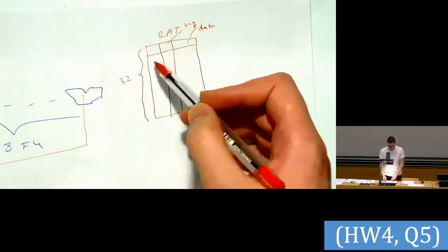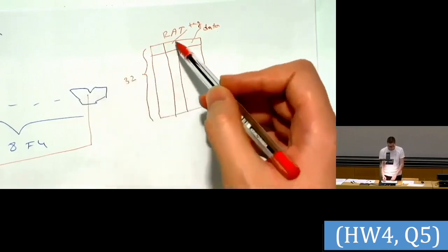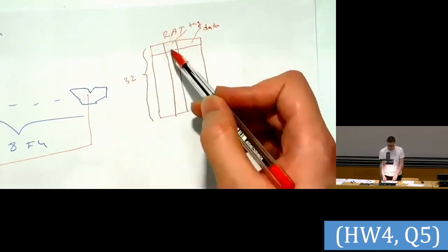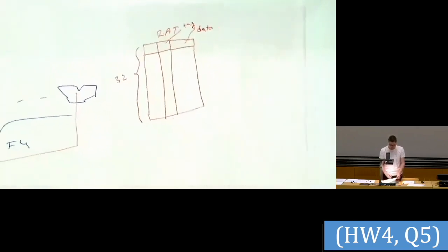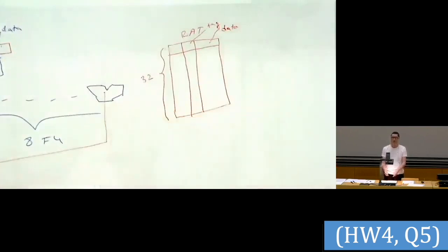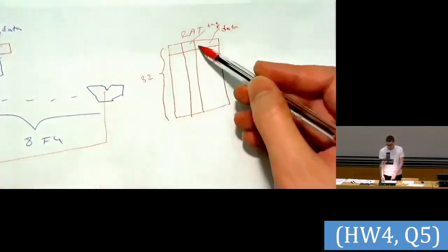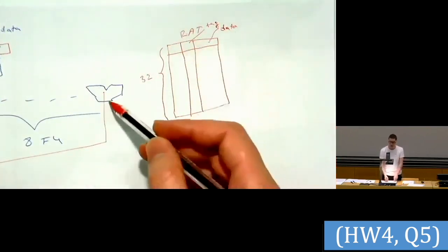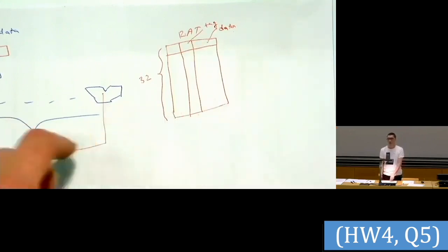So we also have some comparators here, one comparator for each tag. And then it will again be multiplied by the number of functional units, because in a single cycle, we will need to compare those tags against each of the results coming out from the functional units.